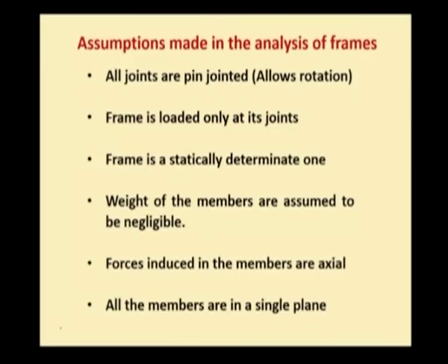Now, let us see the assumptions made in the analysis of frames or trusses. All the joints of the truss are pin jointed. The other name for pin joint is hinged joint. These pin joints or hinged joints will allow rotation, and hence there will not be any moment induced at the joints of the frame or truss.